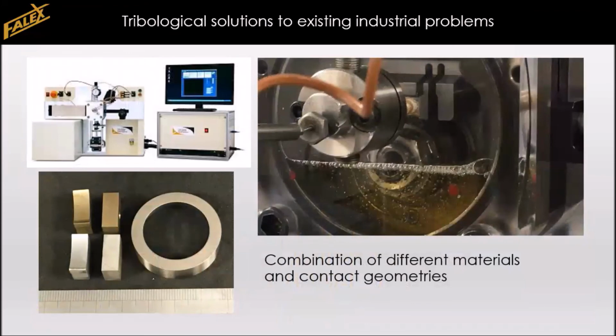Because it's slow motion, we're going to at first simulate this wear mechanism also under slow motion. And we are going to use a Falex block on ring test machine, because in this we can place a ring and rotate it slowly over block materials. The block materials can be a conforming block or a straight block, either creating an area contact or a line contact.